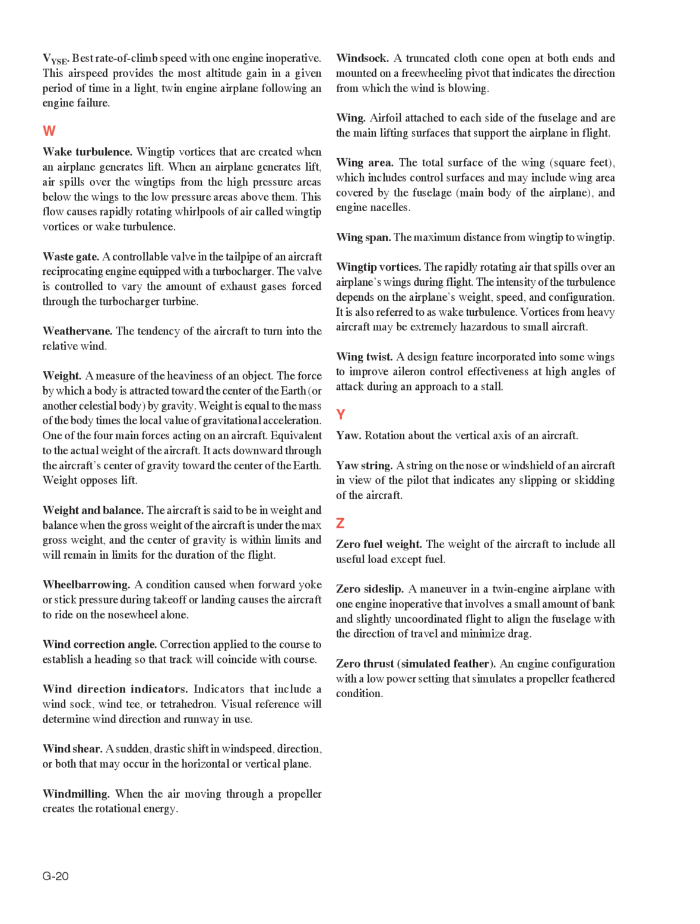Wingtip vortices. The rapidly rotating air that spills over an airplane's wings during flight. The intensity of the turbulence depends on the airplane's weight, speed, and configuration. It is also referred to as wake turbulence. Vortices from heavy aircraft may be extremely hazardous to small aircraft.